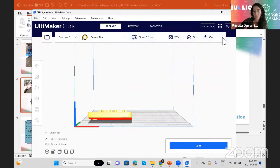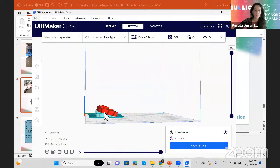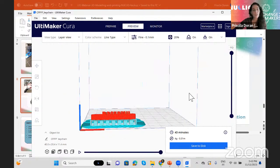Okay, I asked it to produce the supports. And now if I click on slice, it will simulate the layers that the 3D printer will use. And we can preview. It is telling me already that it will take 43 minutes. It will use 4 grams of filament and 0.51 meters. And as you can see, it produced these supports here so that I don't have a problem when creating this keychain. Obviously, this is not efficient.